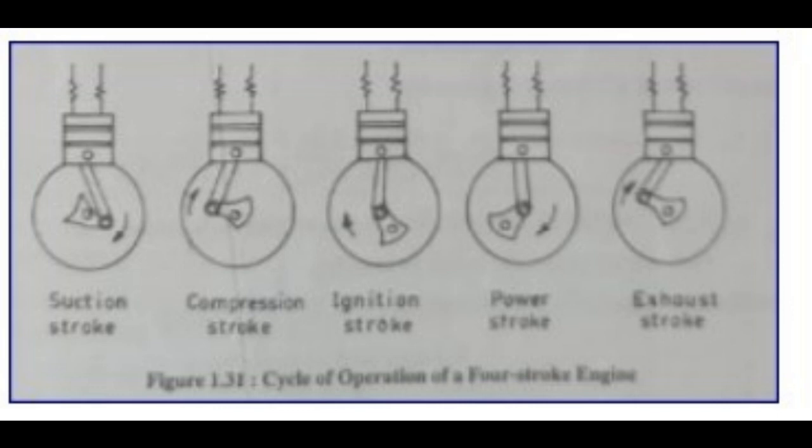2. On the basis of the number of cycles of operation, the automobile engines can also be classified as A. 4-stroke engine, and B. 2-stroke engine. A. 4-stroke engine. The complete cycle of operations in this type of engine is completed in 4 strokes of the piston. These strokes are suction, compression, power and exhaust, as shown in figure 1.31. Look at the screen. A 4-stroke engine has greater piston speed than a 2-stroke engine using crankcase compression.